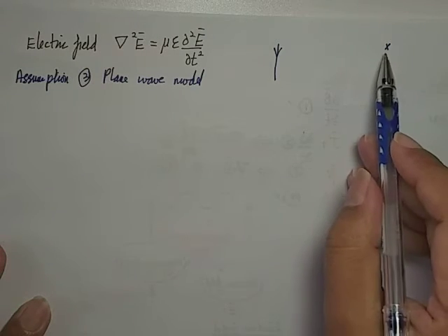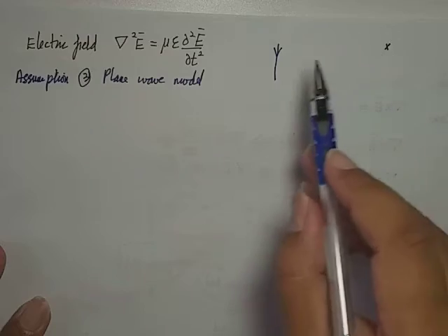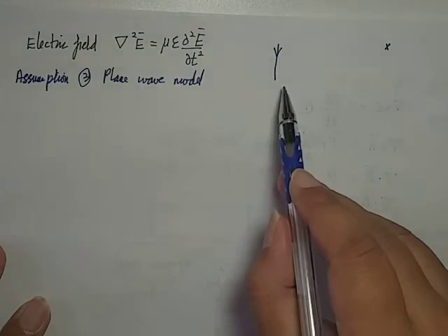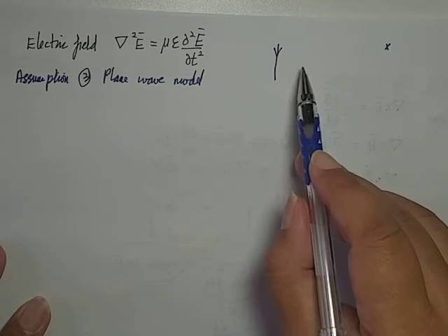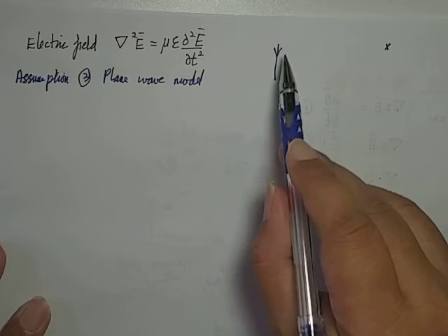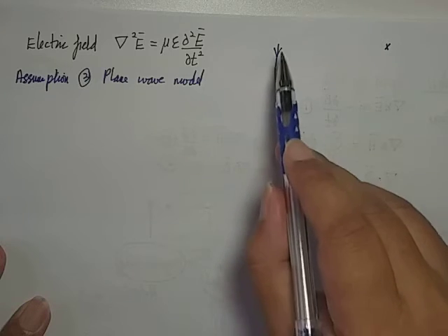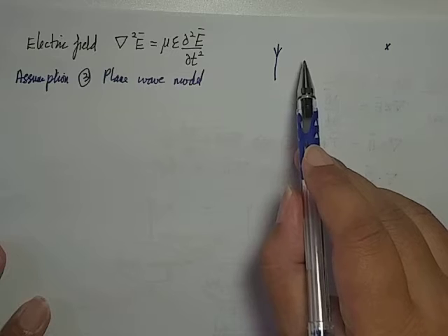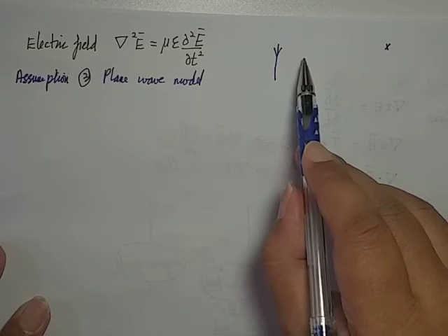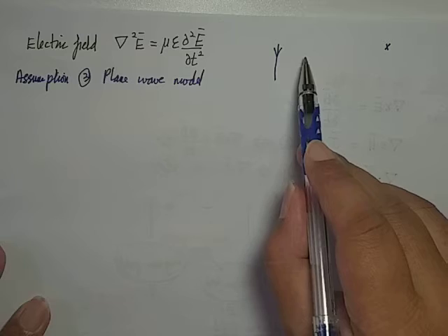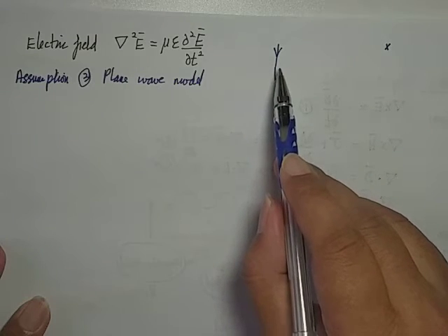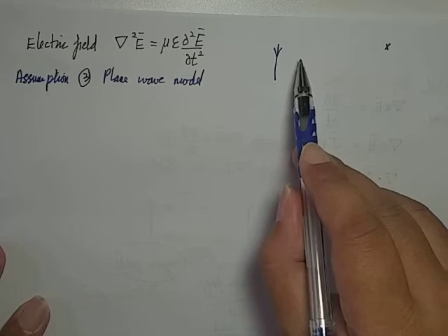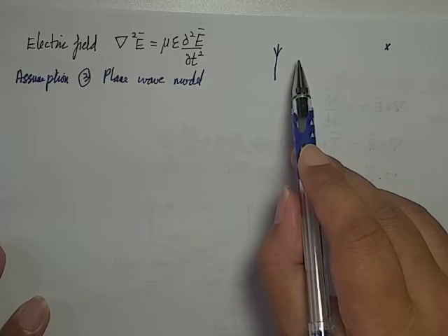Okay, if you analyze the wave close to the antenna, the shape of your antenna will have influence on your generated field. For example, if your antenna appears to be a straight line, you have to use what is known as cylindrical coordinates to analyze the field of propagation, whereas if your antenna appears as a dot, you have to use spherical coordinates as the mathematical model to analyze the field.